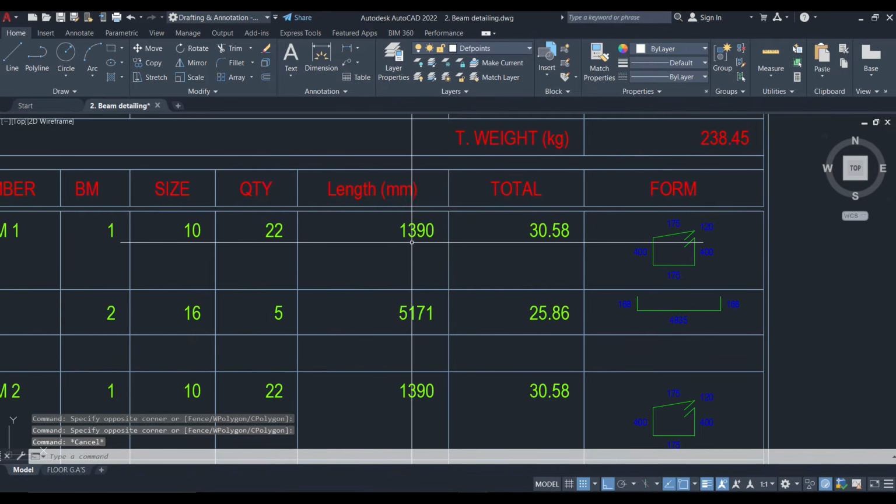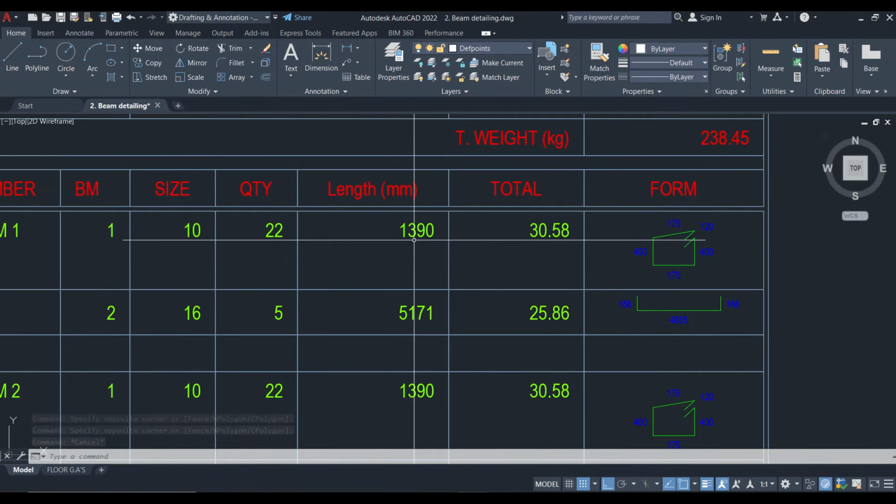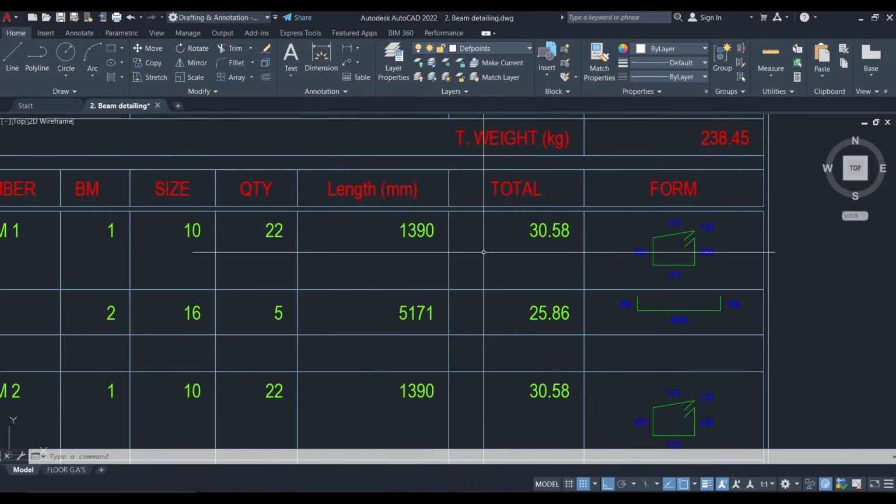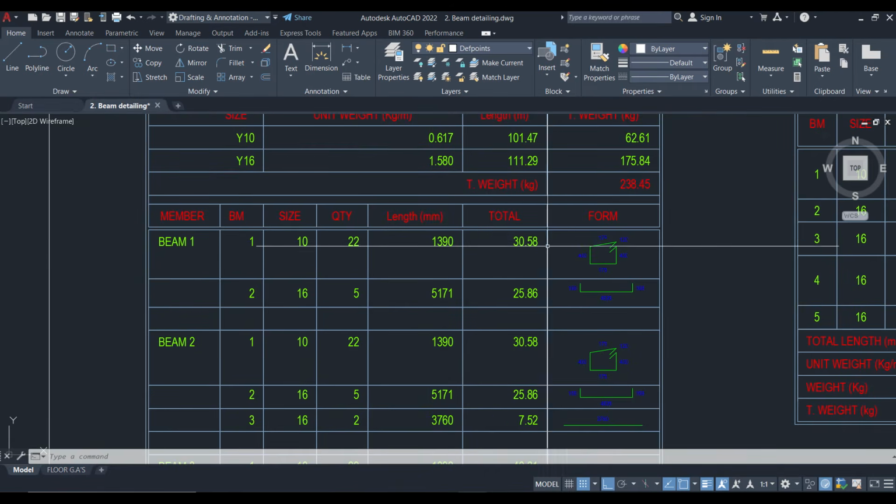It must always be less than 12 meters. When it is more than 12 meters, that means you need to cut that reinforcement and terminate it at a point where the length will not be up to 12 meters and lap it with another bar for continuity. So this is how we record bar mark 1.